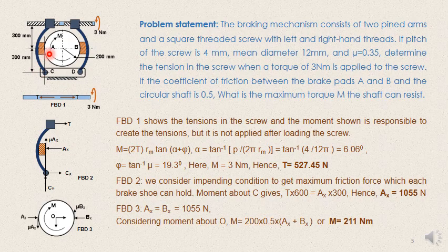There are two parts. One, you have to find out the tension in the bolt. Now look, that is a calculation part. Look from our mechanics point of view. If you are going on tightening, what is happening? This is dragging this side, and this is also dragging this side. So what ultimately will happen to this particular screw? Is the screw in compression?